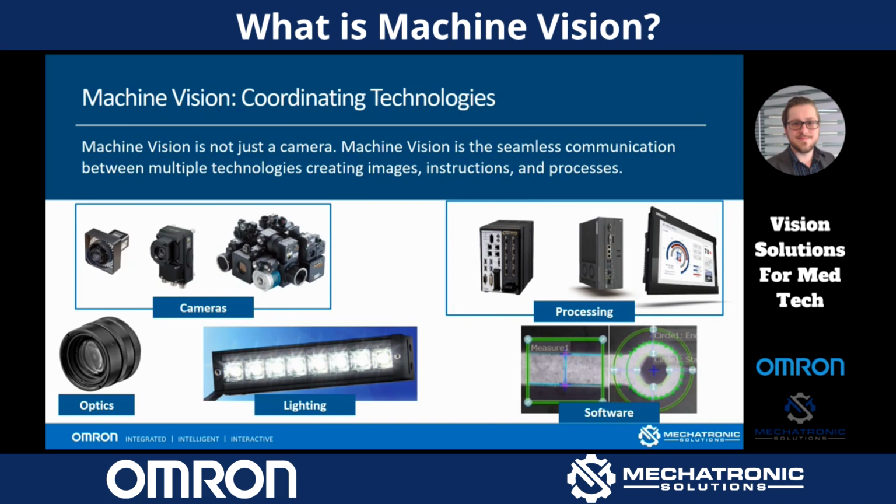If you talk to most vision engineers, one of the things they'll tell you is the most difficult and the most detailed part of machine vision is always lighting. Most of the problems that we've got with machine vision, we can solve with lights. Do you have the proper contrast? Is your ambient lighting okay? All of this is important in putting together a machine vision solution.